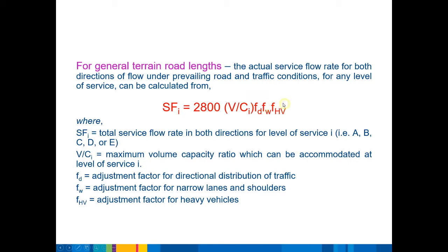So again, if you were reading this out of a design standard, you might have a table that displayed the lane widths, and maybe a 3 meter wide lane has a 0.9 factor, just to make up a number. But that's the kind of thing that we would see here for figuring out capacity. I don't think it's particularly useful, or not particularly important for you to know off the top of your head, but I just wanted to bring your attention to the idea that these things do exist, and if you are designing highways from scratch, you can use this as a tool to make some predictions.